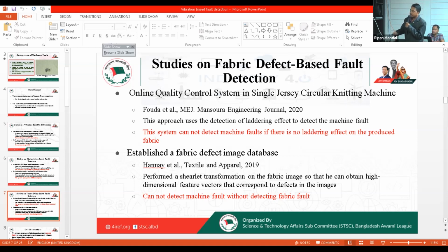These are the 6 faults that we created in our machine. Now, the main components of a knitting machine are needles, sinkers, and cam. The main frequent faults really occur on the needles and sinkers of the machine. So we actually created the most frequent faults that occur in the industry every day.